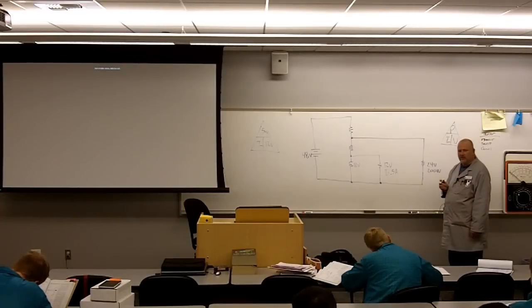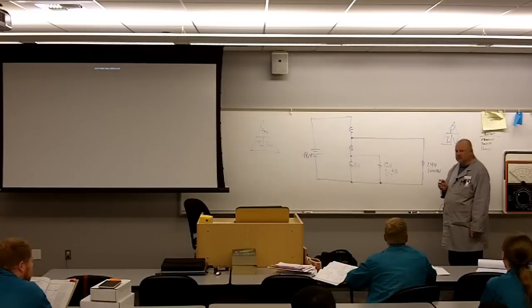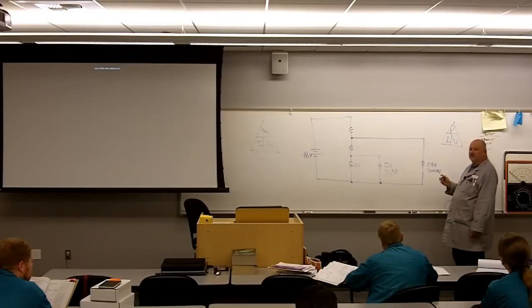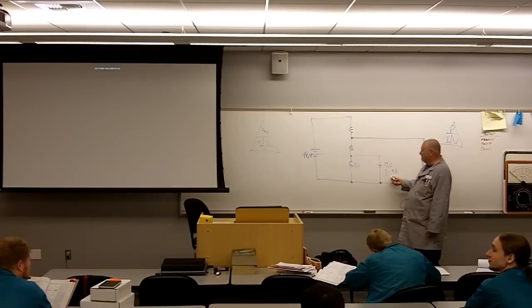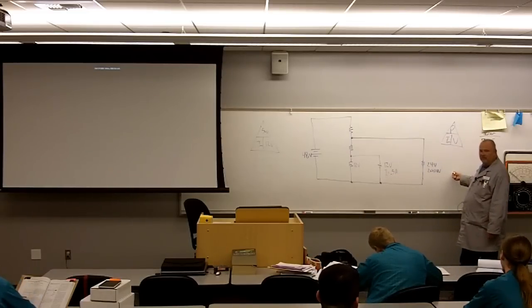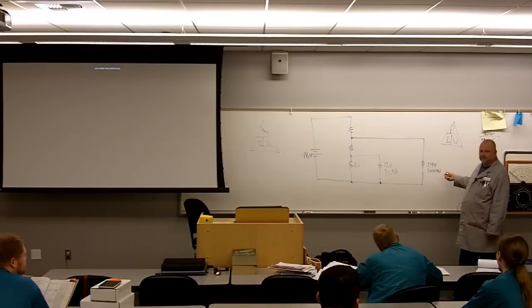How much? 0.12? 120 milliamps? How much? We got a big disparity here. 8.33. That makes sense, right? If a half an amp can power a CB radio, it's going to have to be more than a half an amp to power a 200 watt transmitter, right? Yeah, even at double the voltage.